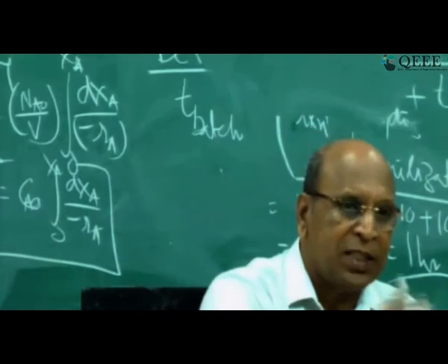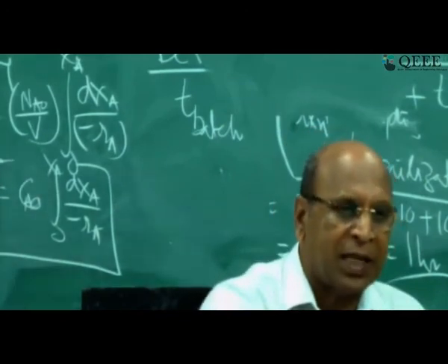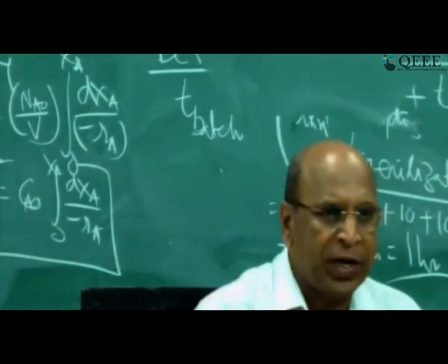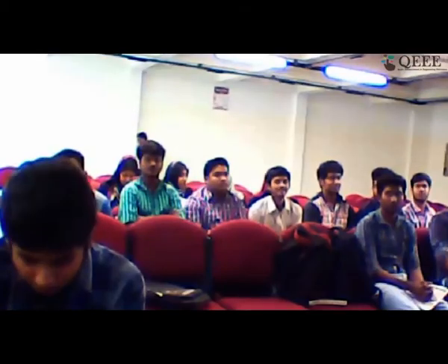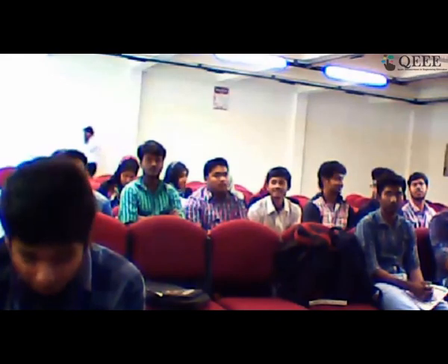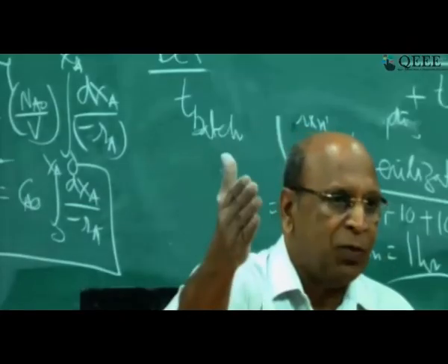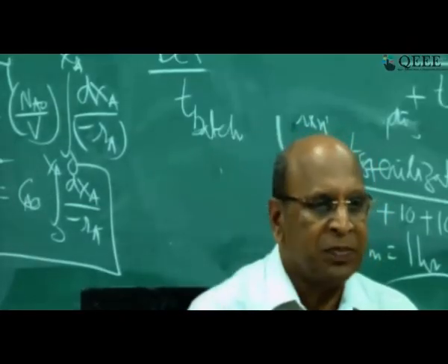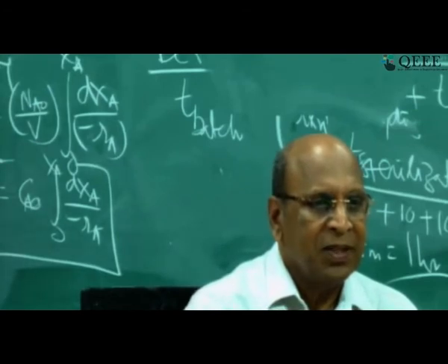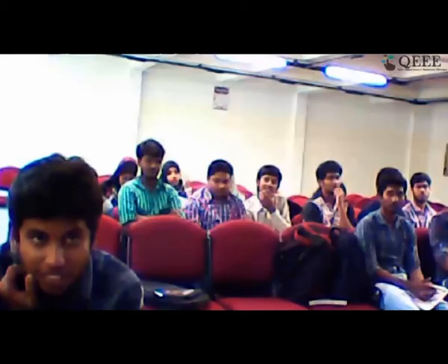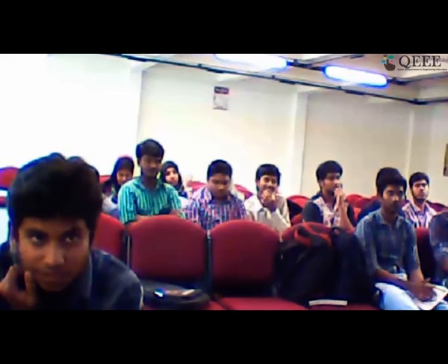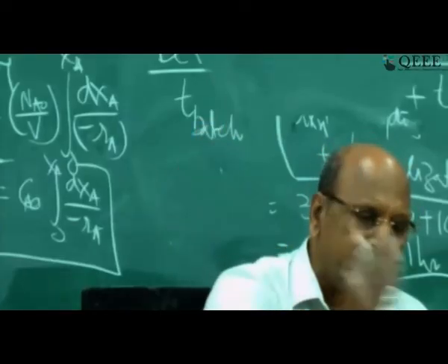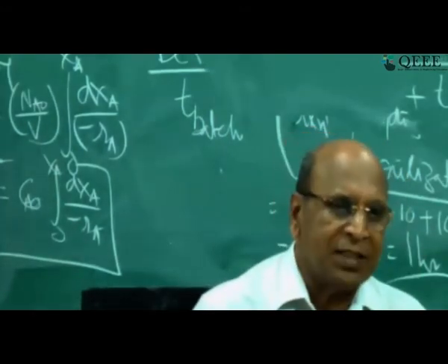But the theoretical value of Reynolds number for ideal plug flow is infinity. Only very high flow rates can give you even the velocity near the wall equal to some value. Sir, it's infinity. That means very large velocities have to be used to achieve ideal plug flow conditions.